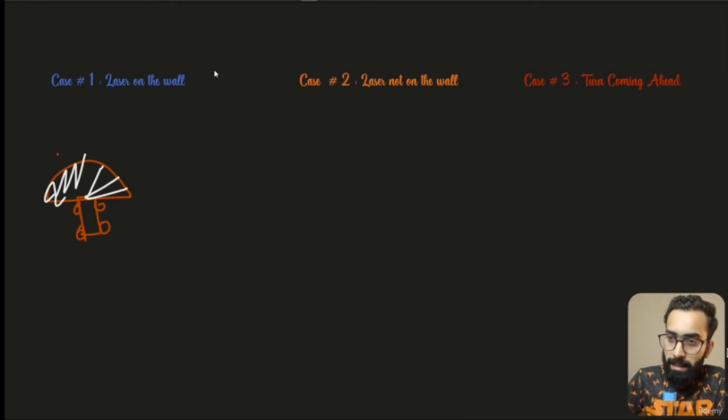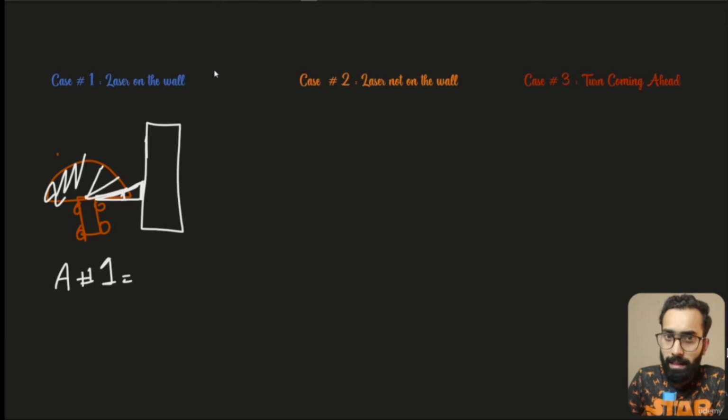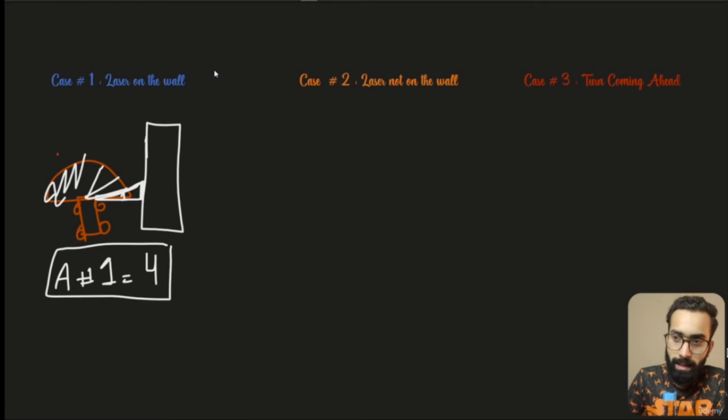Now, this area number one here is going to be the main area, which is going to find the wall and keep a specific distance from the wall. Whenever there is a wall, this area is going to detect it. Let's say the span is from this point to this point, and it will say that I have an object in area number 1. As we discovered in the previous project, we can find any object in a certain area. We can tell area number 1 value is less than 100, less than infinity, less than 100. I've set it so that if the value of an area is less than 4, there is a wall in that specific area. Whenever area number 1 has a value less than 4, which means there is a wall, keep the robot moving. We have found the wall. That is the basic concept of following the wall.